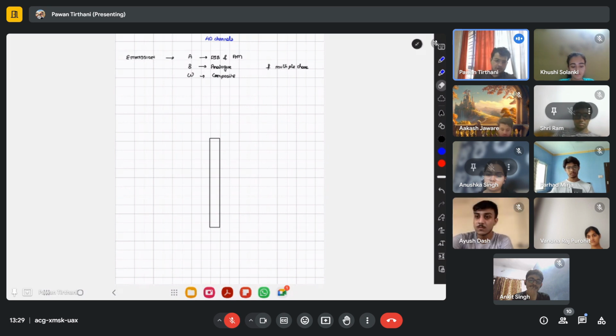Okay, you haven't been taught what a visual circuit is. So a visual circuit is a pattern that we follow around a runway for the purpose of practicing approaches and landings. Okay, and by looking at the visual ground aid, which is nothing but the runway. What do you do in a visual circuit?